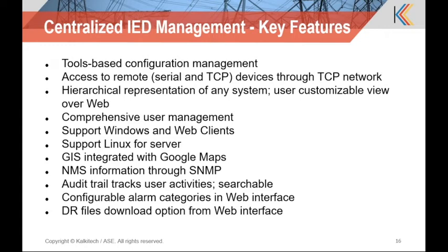Then it has a GIS-integrated Google map, so all the live, communicating substations can be indicated over the Google map. You click on the corresponding map window, and from there further analysis and further download are possible. Then detailed network management is available, and this information is available through the Simple Network Management Protocol, SNMP. An audit trail is available to track details of user activities. Multiple security levels are available. Then configuration alarm categories are in the web interface, and disturbance record or fault file download options from the web interface are available. So centralized IED management using PSCS is one of the key features we offer with this package.